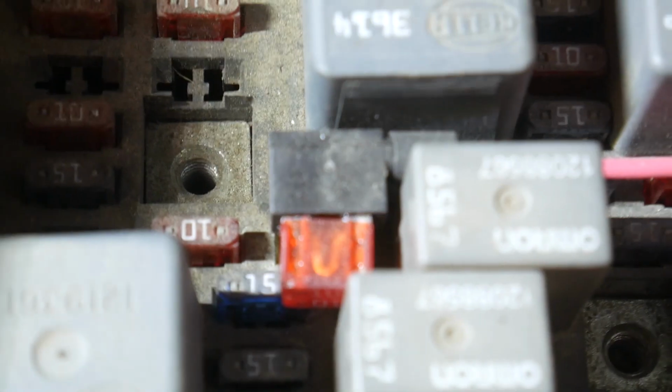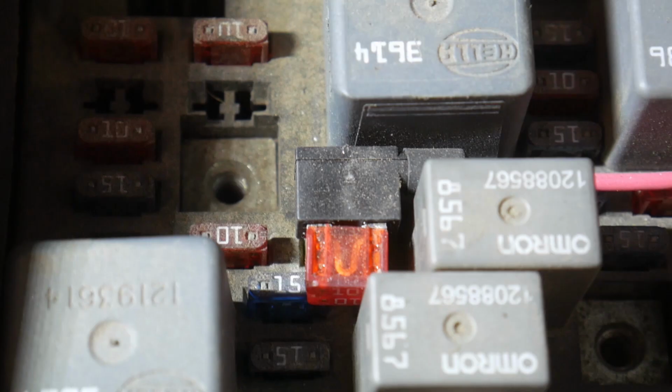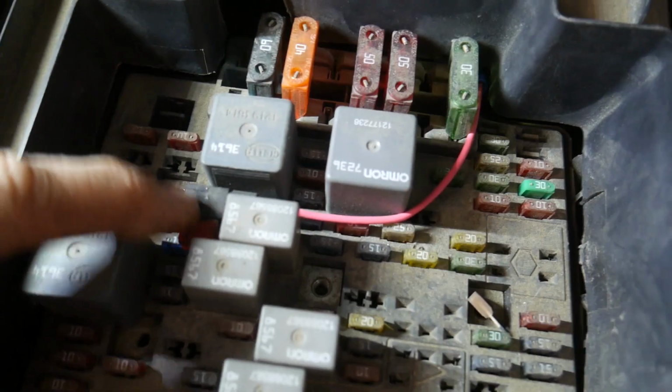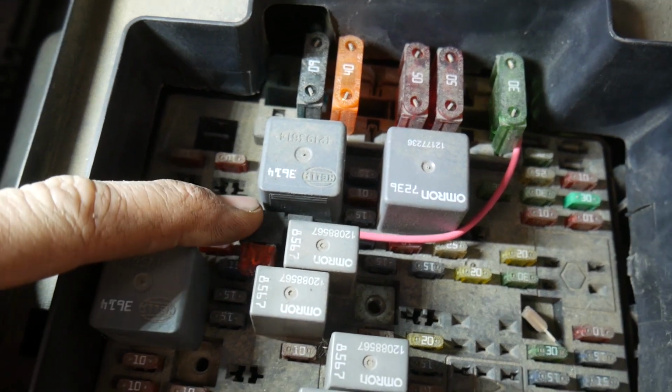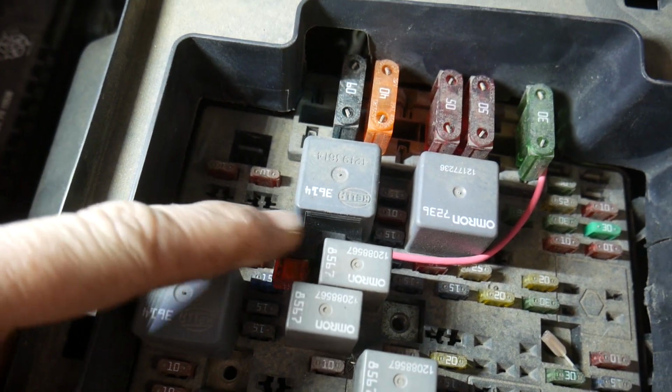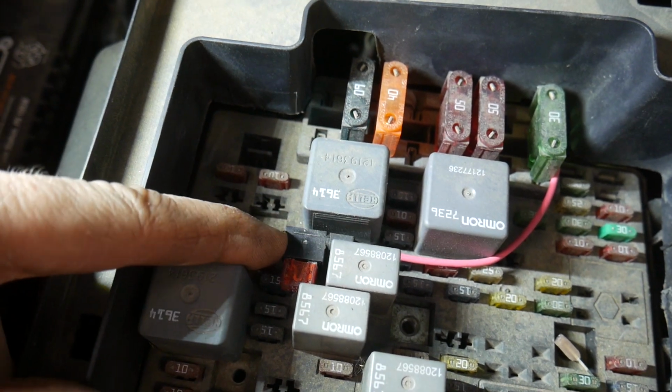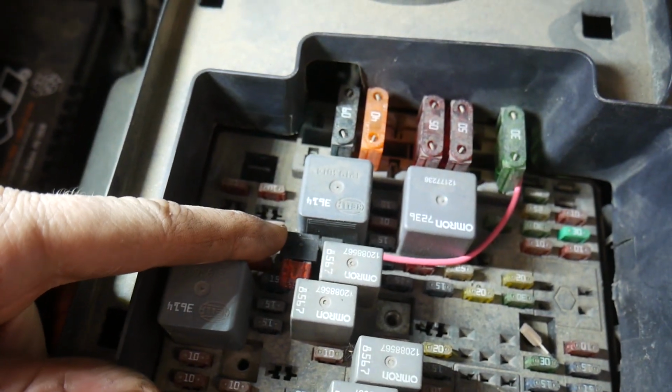be a 10 amp. If we look in here close, you can see a little bit of corrosion on that fuse. That fuse looks good. The one below it, it's hard to test it because the relay is right in the way. Me personally, I would not put a fuse tap into anything that is operated or going to the ECM, they should have tied into an accessory fuse.